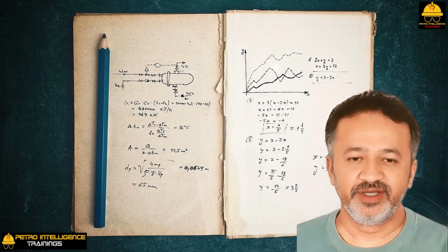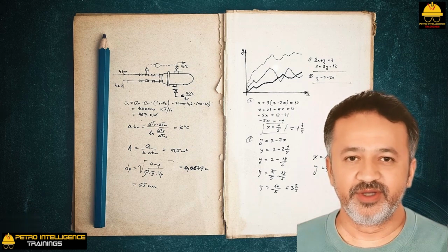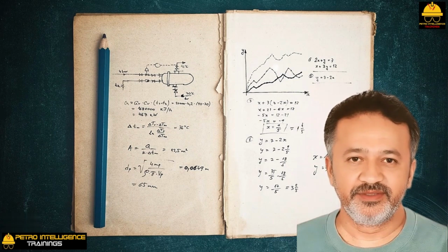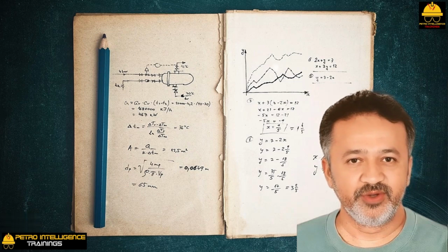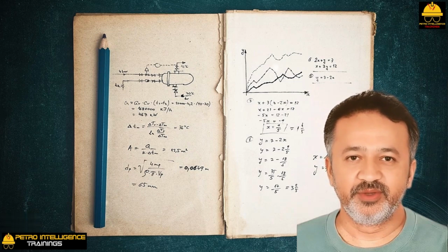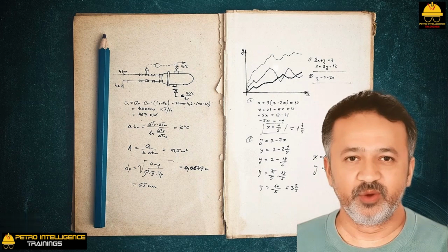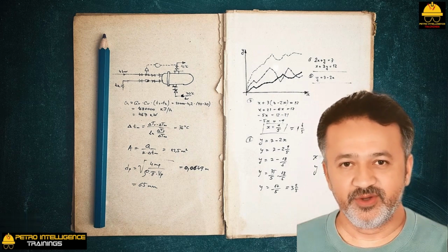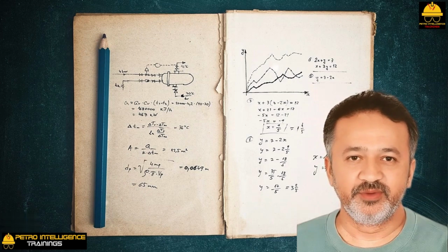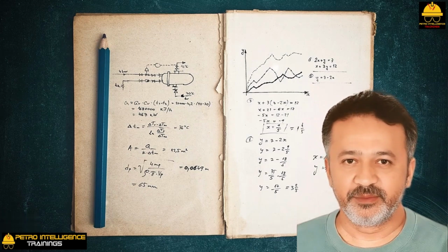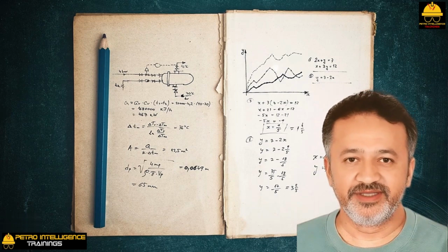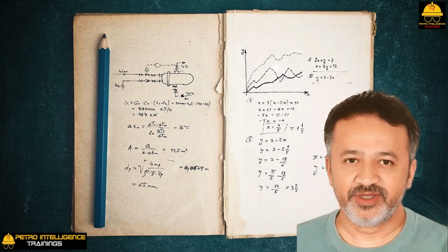For those of you who work in the liquefied natural gas industry, all the discussed principles relating to steam apply to light liquid hydrocarbons as well. The Rotoflow turbo expander, which you use to partially liquefy the natural gas, is much the same as a steam turbine. That is, the motive gas is partially condensed to ethane and propane, as the temperature of the gas is converted to velocity, as the gas flows into the Rotoflow turbine case. Much of the torque developed by the expander turbine is derived from the latent heat of condensation of the liquefied petroleum fractions.